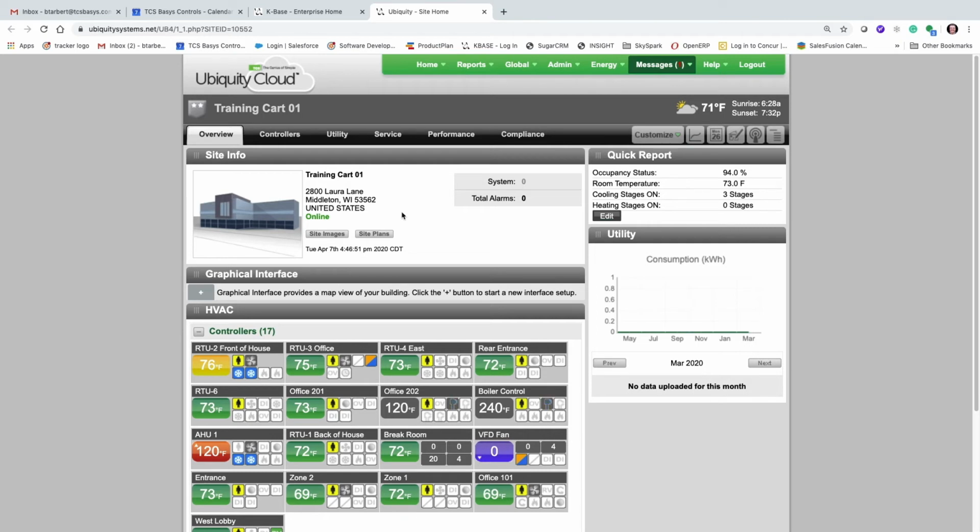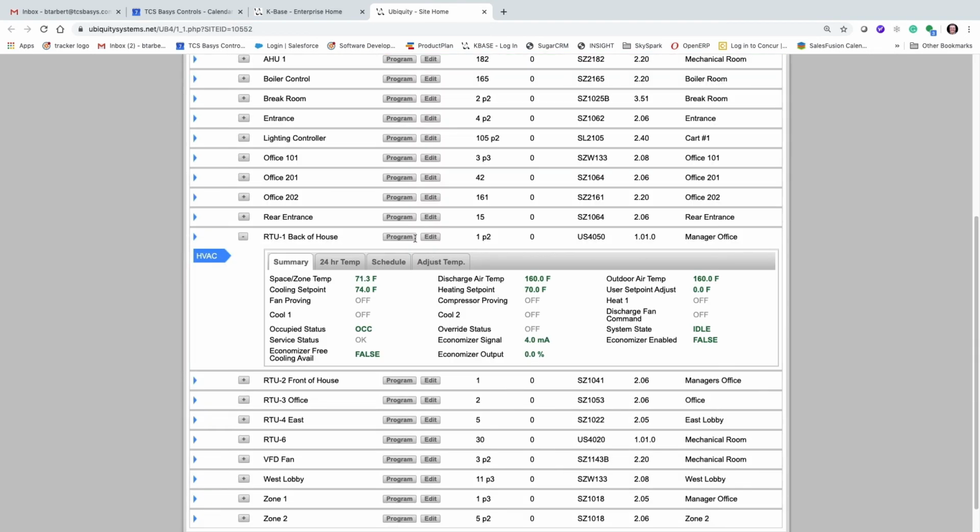In this video, we'll show you how to set up the different setpoint groups and also how to select the override setpoint pair. So I'll demonstrate how to match up occupied setpoint groups to different occupancy schedules, and then also how to program which setpoint group will be used whenever a thermostat is overridden at the site from the unoccupied to the occupied mode. So to begin with, we'll go ahead and select our controller and then go right to